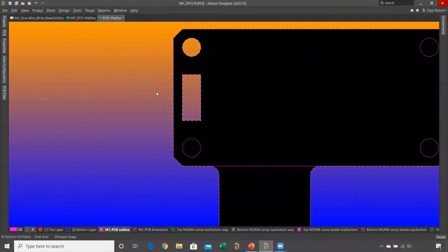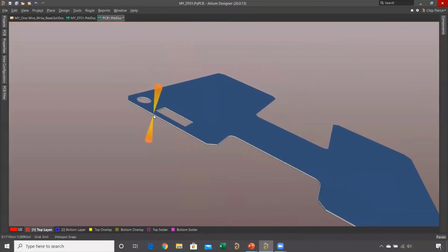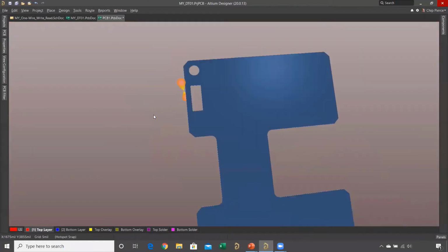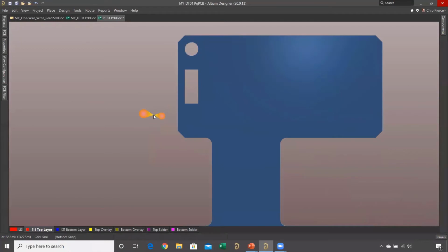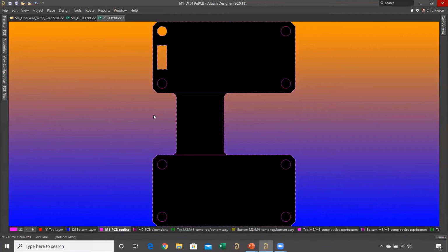So you'll see that very often, your mechanical engineer hopefully would give you that board shape. You see that? And that's the way to go, okay? And now I'm just going to hit the 0 key to set the 0 axes, VF to fit the board, and now I hit 2 to jump back into 2D mode. And of course, you see that in 2D mode, there are 2 different zoom settings.